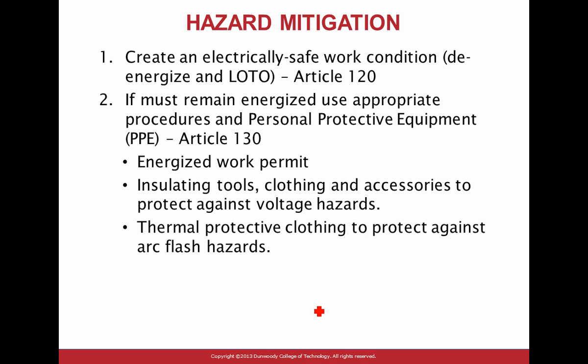It was something like 120 calories per centimeter squared, and 40 calories per centimeter squared is the max, which is category 4. So between 40 and 120, the software tells you immediately that this piece of equipment shall not be worked on energized. So what do you do? Contact Excel, let them shut down and work, lock it, tag it, do the procedures, then work on it. You guys don't have to worry too much about this one; at your level, you wouldn't encounter that.